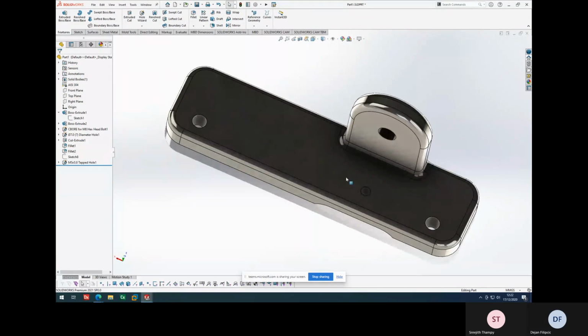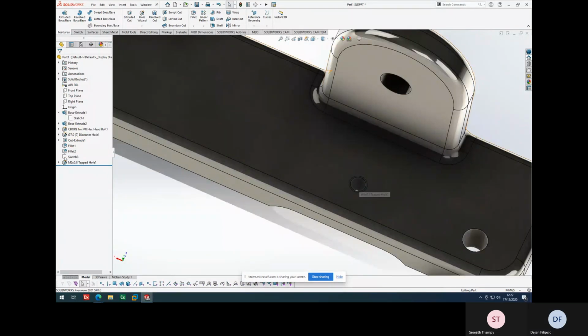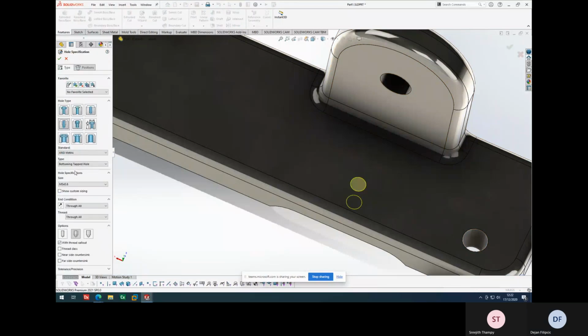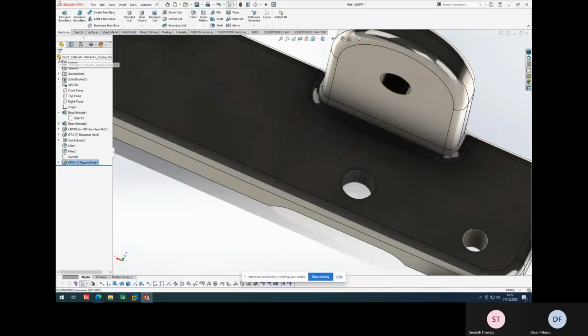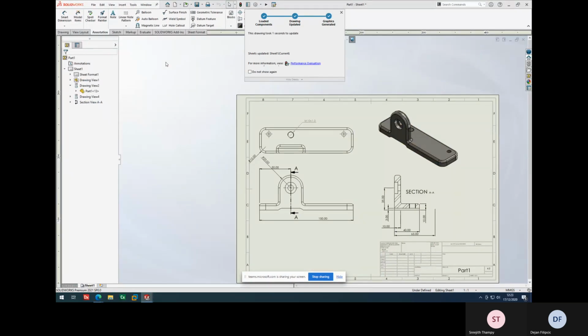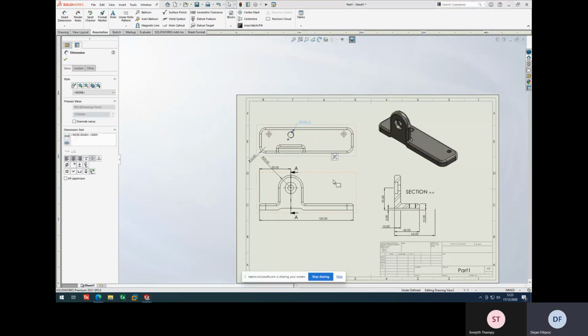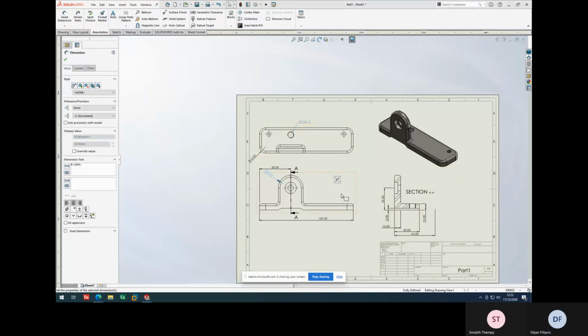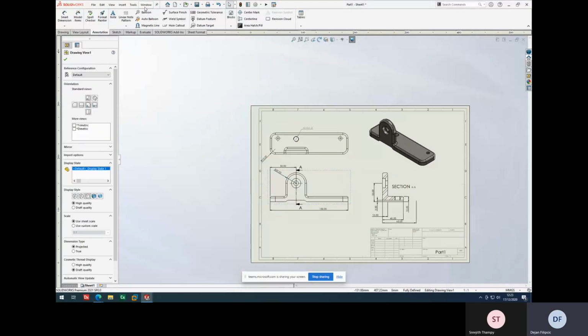Changes in the model. And here I change the thread size. Let's see whether the thread size will update there or not. I have made it M5, but I don't want M5. Later I decided I wanted M10. So I go back to the model and check whether the software identifies it. Yes, it identifies it and it's changed. And this is the associative feature of SolidWorks. Whatever we are creating there is updated here, and whatever we are changing here will be updated there as well. This is the beauty of these softwares.